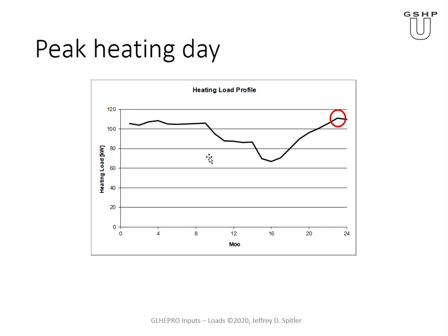There's also a monthly heating load, and so if, say, that's 40 kilowatts of heat extraction, then we would actually superimpose a load that would be the difference between the heat extraction load with the actual and the constant for the month, and that would be the load we'd superimpose on the ground heat exchanger. So in the Introduction to Ground Heat Exchanger Modeling lecture, there's some explanation of the superposition process.